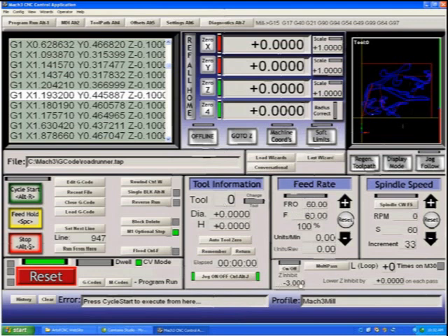This section of the screen here is used for multipass. Again, you don't need to worry about it unless you know how to use it. Generally though, if you have a G-Code file which is set to a particular depth, say it's set to cut to -10, you could hit multipass and tell that file to cut 5 times, dropping 2 each time, until it hits -10. So it is literally a multipass selector, allowing you to cut a file in multiple passes.